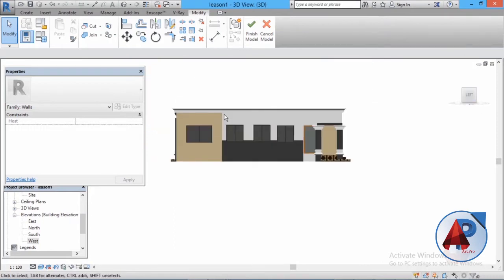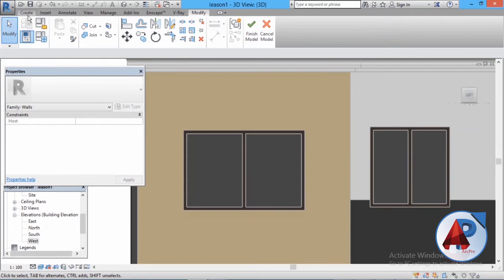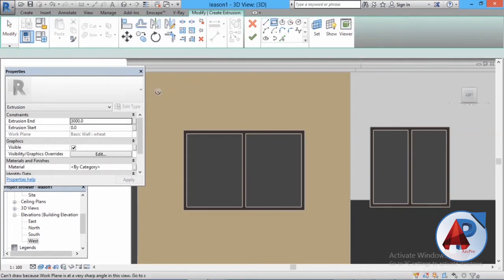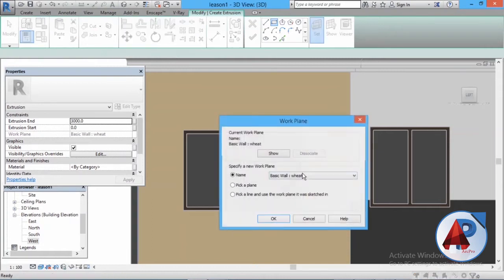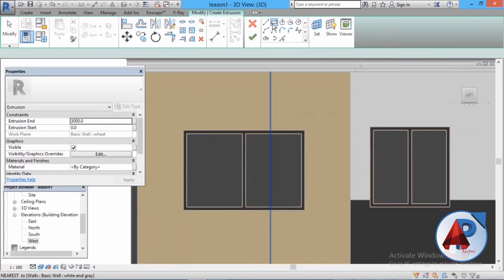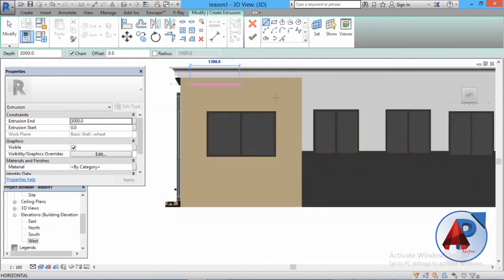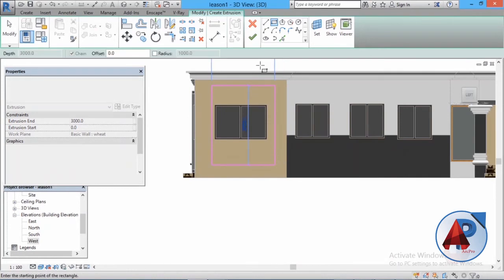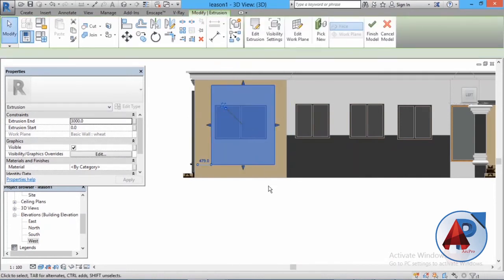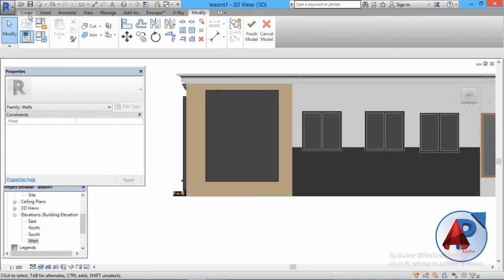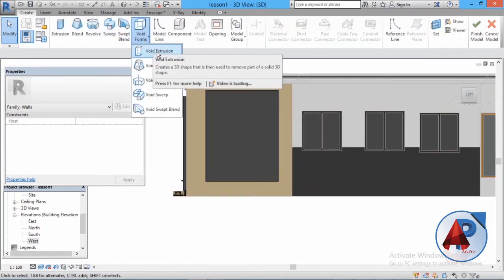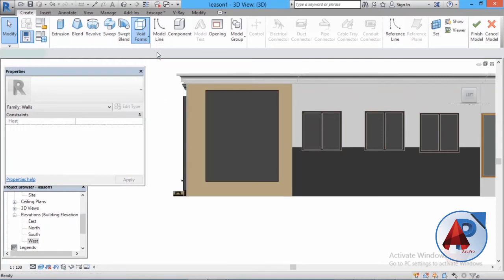and you face this side and try to achieve something here, extrusion, maybe set wall plane, pick a plane, okay, pick this plane, get this rectangle, and I create this. If I save it, now it's over in this side, so I still need to go and create a void by extrusion, because that's what I made, void by extrusion.